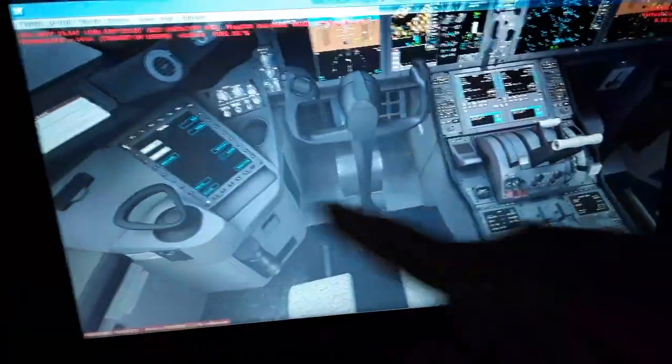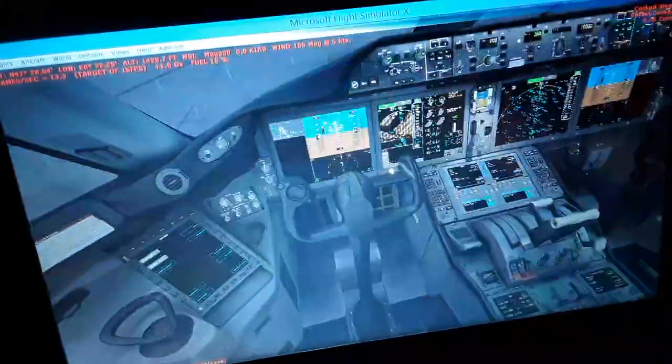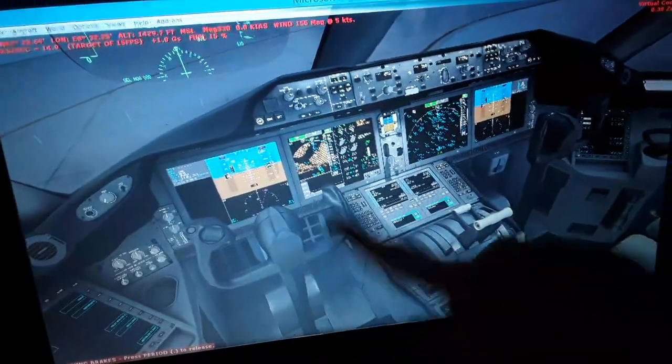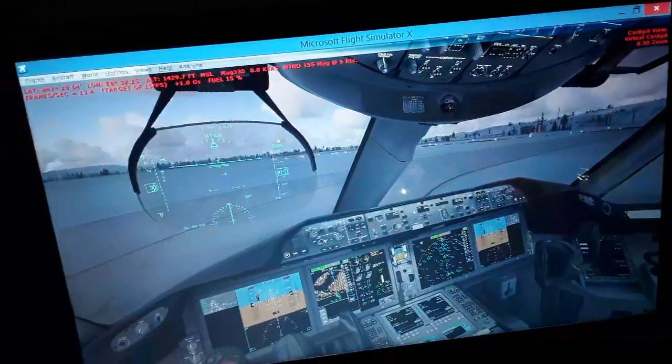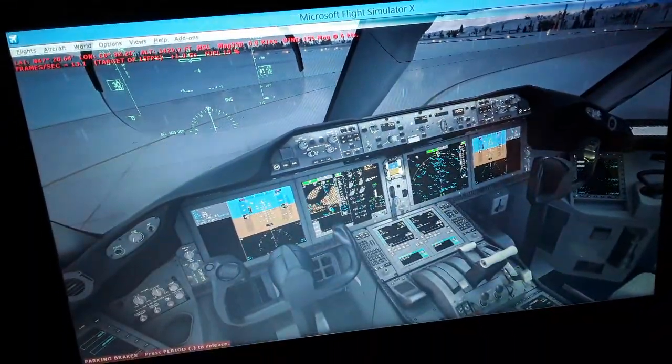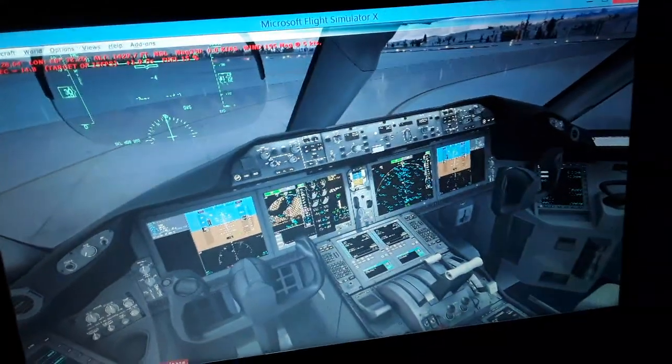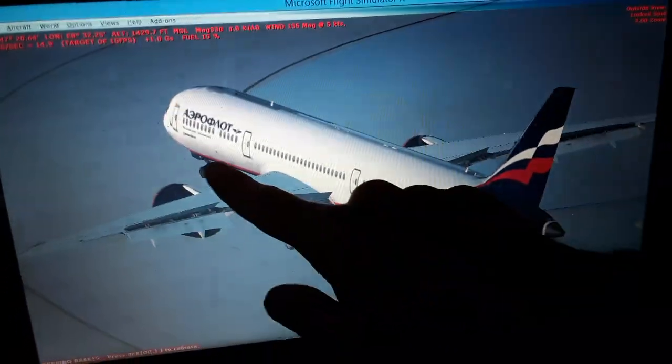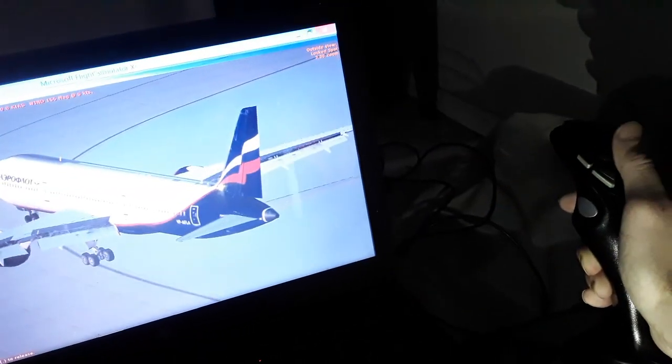We also have the tiller for controlling the nose wheel steering, and also the rudder pedals simultaneously. In takeoff, we have only the rudder, so we lose the nose wheel steering; it locks at zero deflection. We have only the rudder aerodynamically effective.